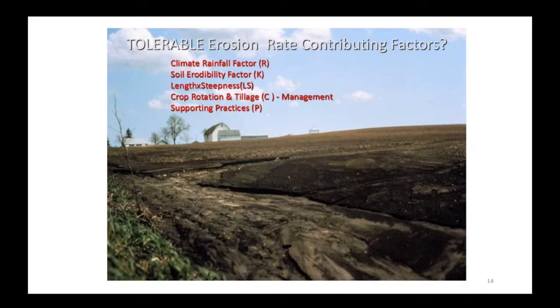So soils that have a high K, in Wisconsin we can be up to a 0.43, and what that means is that there's a ratio of the soil and the slope steepness, and then it's tied into rainfall events. But if you keep one thing in mind about the soil erodibility factor, it is that the K factor is most erosive for silt loams.